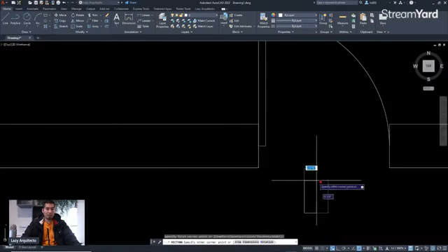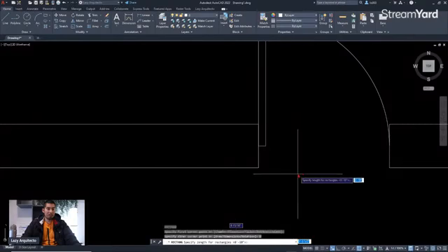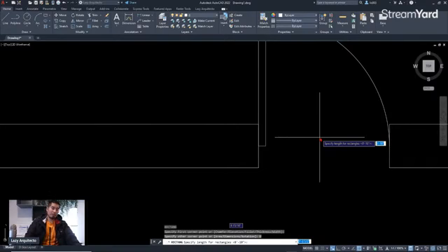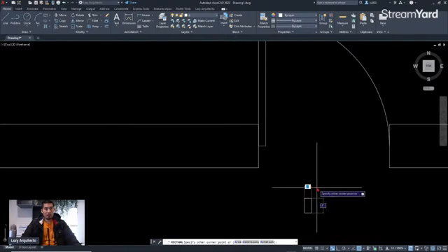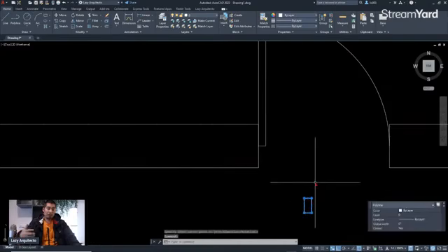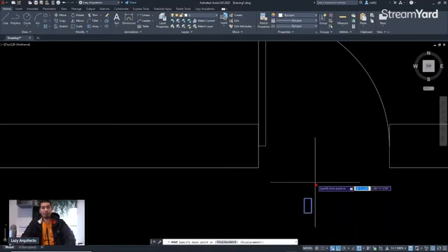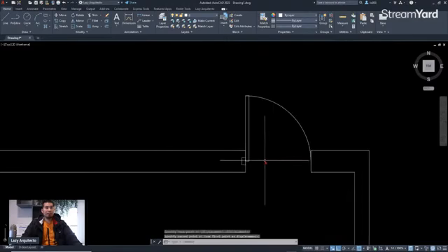I'm gonna click over here, and then using the options, I'm gonna click dimensions, and then I want 2 inches by 4 inches, and then click anywhere on your screen. So I'm gonna click here like so, and then using the move command that we previously used with its shortcut M, gonna click over here, click, and then place it like so.